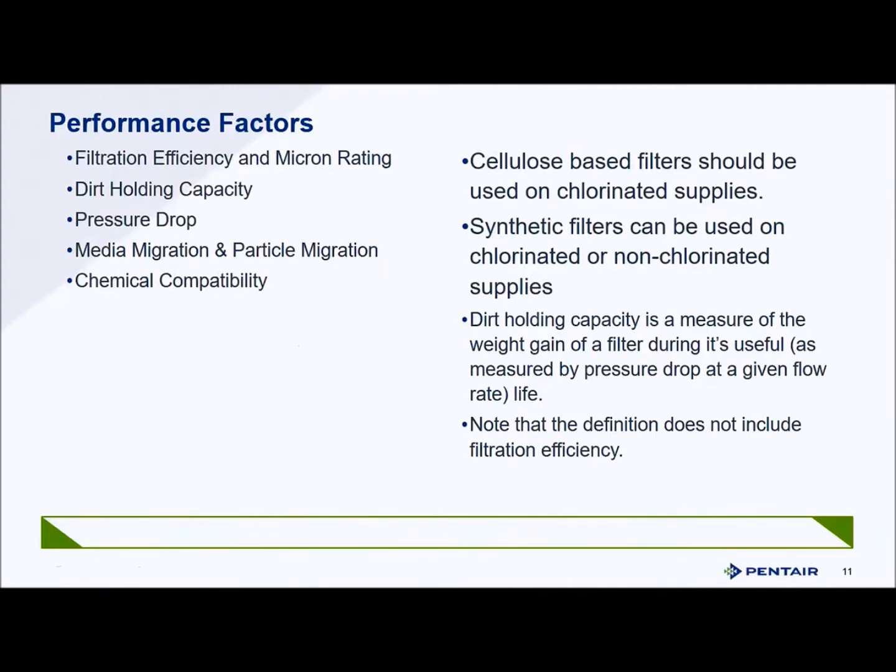Pentek filters are rated based on real world water qualities and average tap water quality, tested at NSF, not laboratory water free of debris. We want to understand how they perform in real world applications. Pressure drop across a filter as it loads is critical. Pressure is the driving force of all filtration.